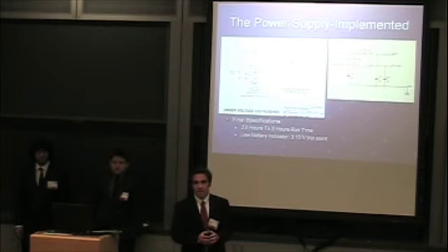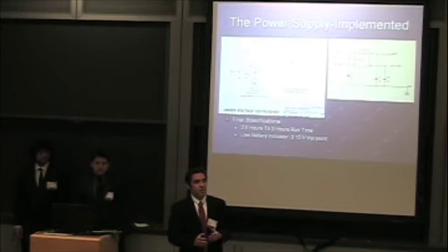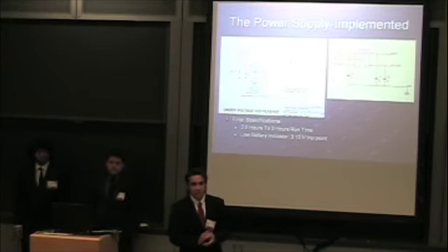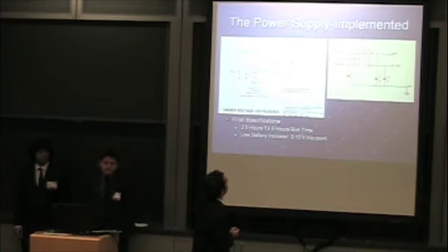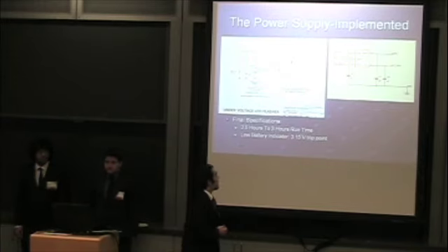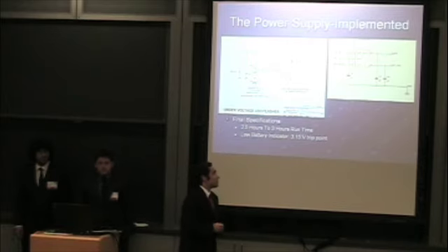Our trip point needed to be somewhere between 3 and 3.2 volts because the device requires a minimum voltage of 3 volts to be on. So there was manipulation done to the resistors that set the charge time of C2 in the schematic to change the trip point to 3.15 volts.